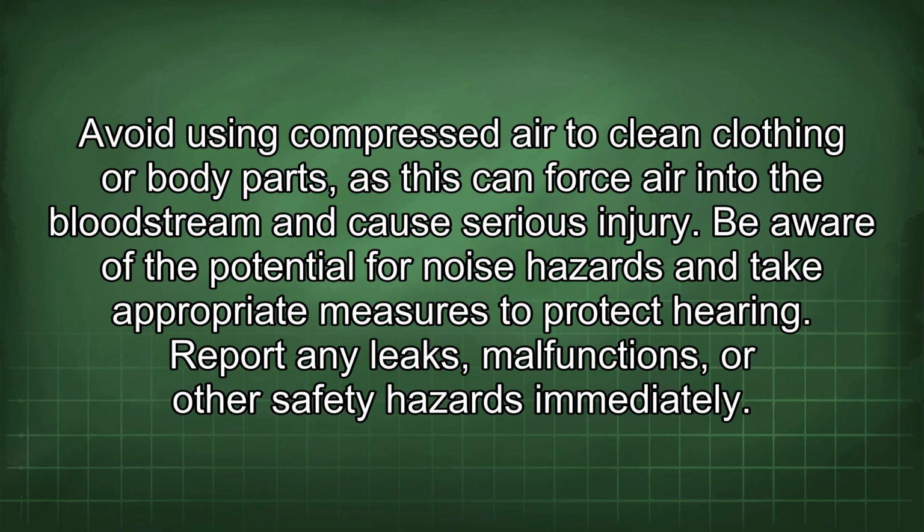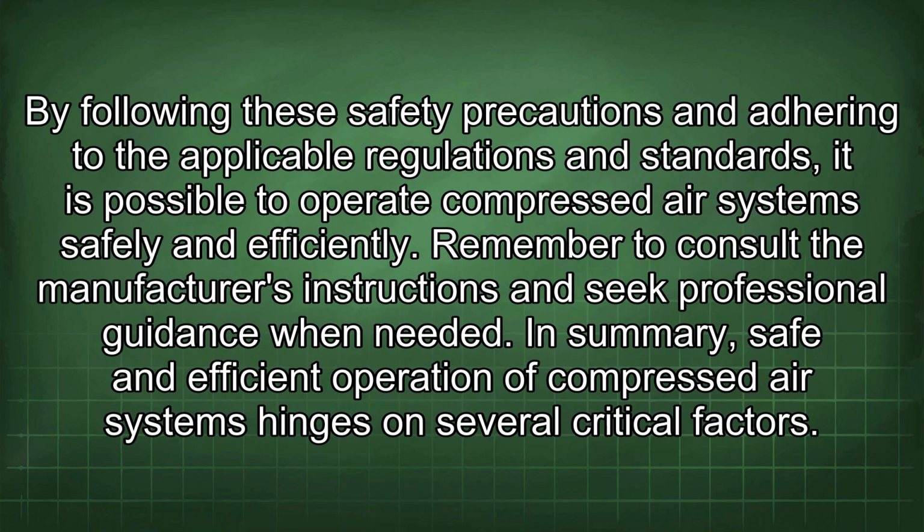Avoid using compressed air to clean clothing or body parts, as this can force air into the bloodstream and cause serious injury. Be aware of the potential for noise hazards and take appropriate measures to protect hearing. Report any leaks, malfunctions, or other safety hazards immediately. By following these safety precautions and adhering to the applicable regulations and standards, it is possible to operate compressed air systems safely and efficiently. Remember to consult the manufacturer's instructions and seek professional guidance when needed.